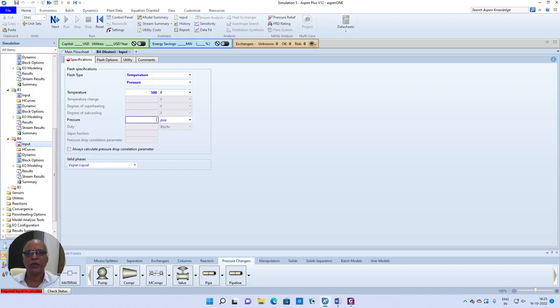The pressure, this is a heater. Again, like what we have seen in the previous case, let me assume that there is no pressure drop in this heater block. Remember, we don't know to what intermediate temperature we need to heat the liquid ethyl benzene and vaporize, such that when it is compressed to the required pressure, ultimately it should be at 752. We may not be able to know the temperature to start with, so I am presuming a value for this. Now go to the next input.